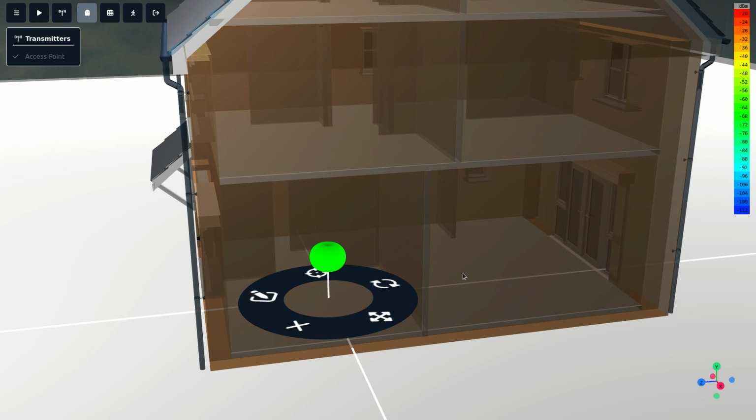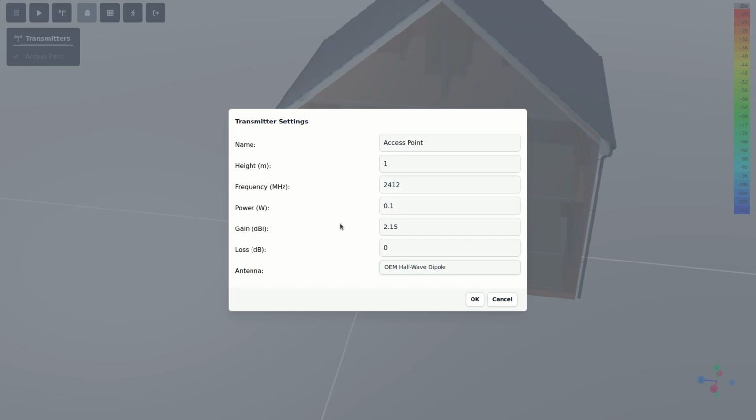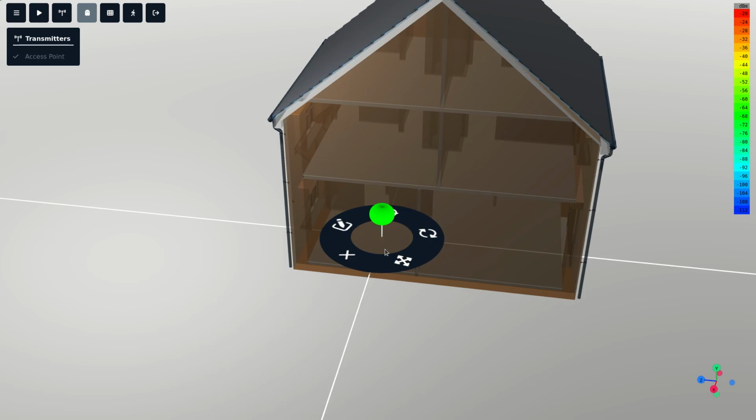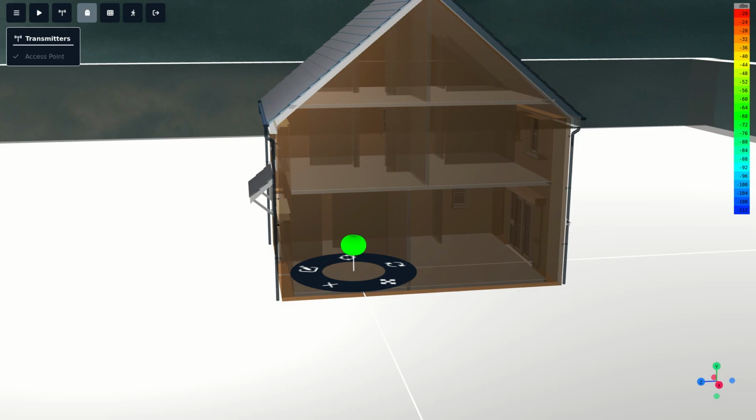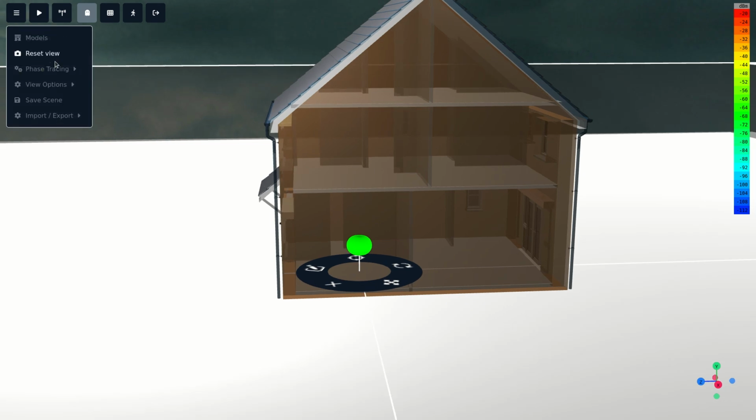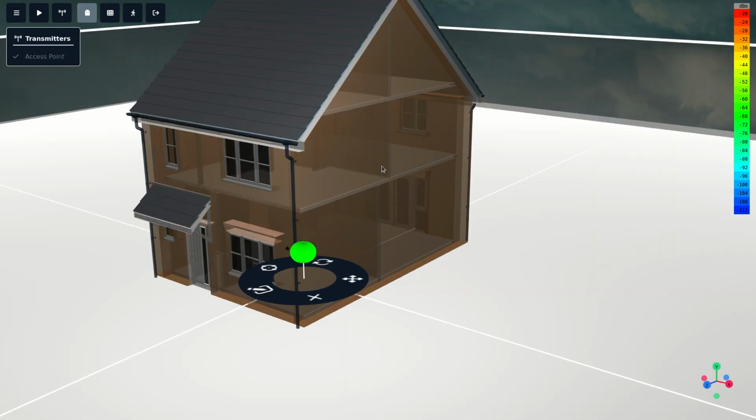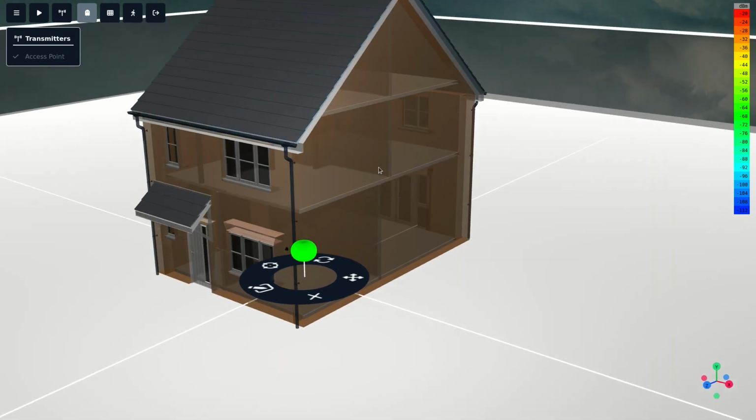And for this AP we're going to configure it to represent European Wi-Fi parameters. In this case Wi-Fi channel 1 down near the ground, 100 milliwatts of power, and it's just a dipole antenna. So on the phase tracing menu in CloudRF, I'm going to select high resolution, reflections high, so about 20 reflections, and density high.